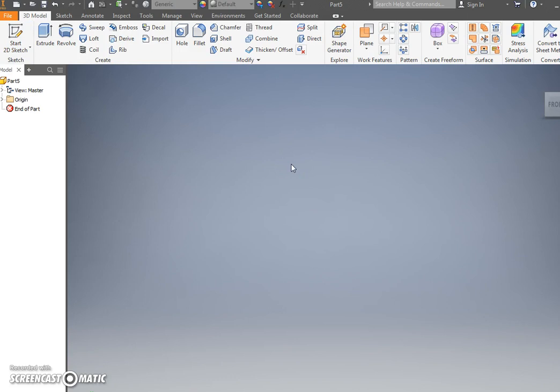As my computer slowly loads, it looks like it is loaded. You'll see it starts off as more of a 3D interface with your extrude, revolve, sweeps, holes, that kind of fun stuff. This is your ribbon. This is your project browser. Do not close this down. There's a few new features here. Maybe you figured it out, maybe you didn't. Do not close these out. It looks like they're a little bit harder now to close out with expand all stuff. But please leave it open because this is going to be your history of what you've done.